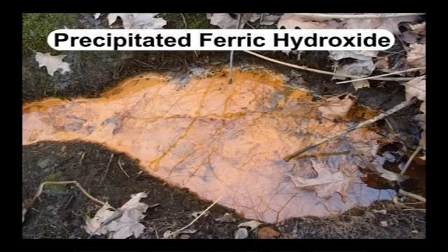An inherent problem is that trickling filters can be blocked by precipitated ferric hydroxide and carbonates with concomitant reduction of microbial activity. In the case of overloading with dairy wastewater, the medium becomes blocked with heavy biological and fat films. Biological filters are not appropriate for the treatment of high strength wastewaters, as filter blinding by organic deposition on the filter medium is generally bound to occur.